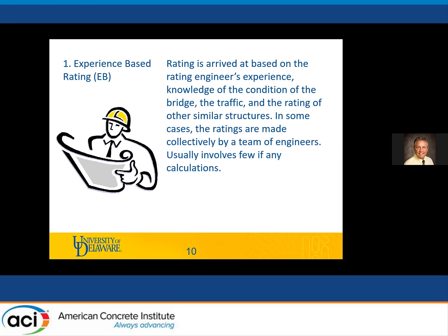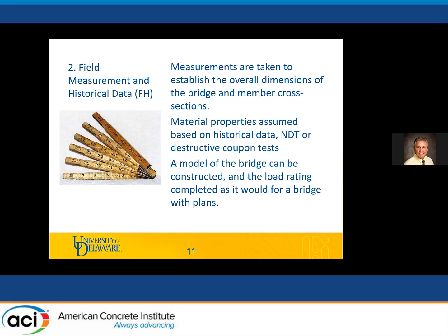Experience-based is, just as it says, when an engineer uses their experience and knowledge of how bridges behave to come up with a load rating. Field measurement is primarily used for timber and steel bridges. This is where they go out and get field measurements, perhaps coupons. Once they have that information, they can develop a model of the bridge and do the load rating.